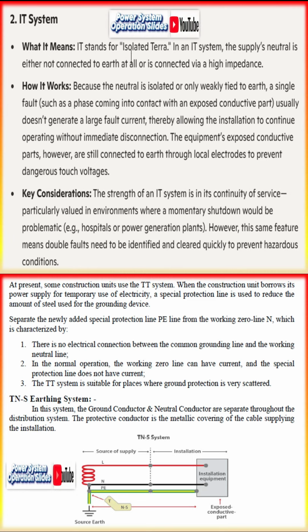Key considerations: the TT system is appreciated for its immunity to certain types of interference that might arise from the utility's earthing system, but it demands careful attention to earth electrode resistance and robust fault protection at the consumer premises.